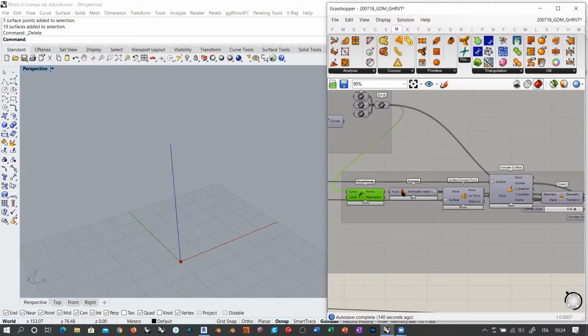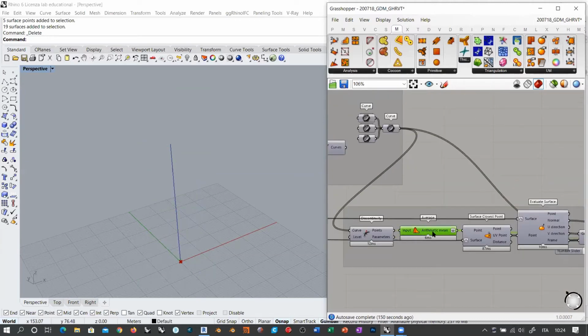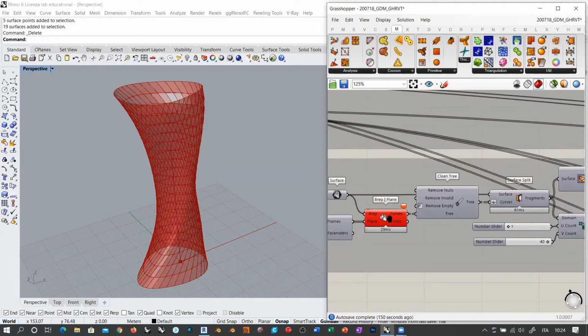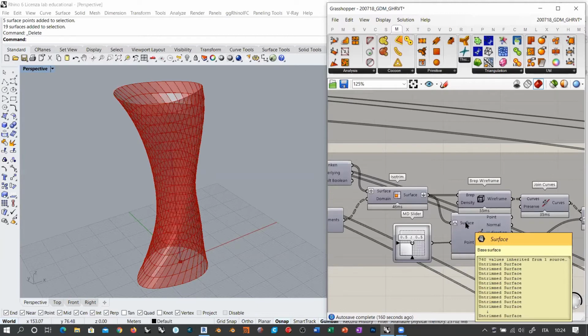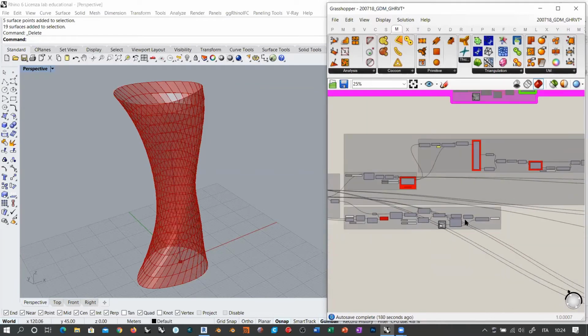These are the discontinuities. I was calculating the average point. The reason why I did this is because when you have a rectangular shaped panel, you can use, for example, the evaluate surface, because topologically speaking, they are basically a square or rectangular panel. So you can use this in order to obtain the center point, and also the center orientation, so the frame, in order to obtain the projection. Okay, but when you have a hexagonal panel,